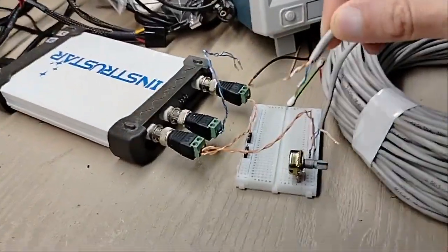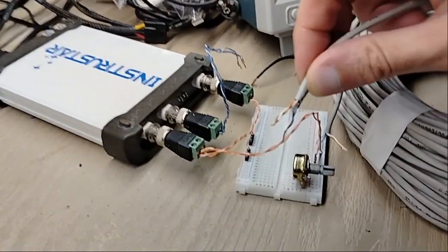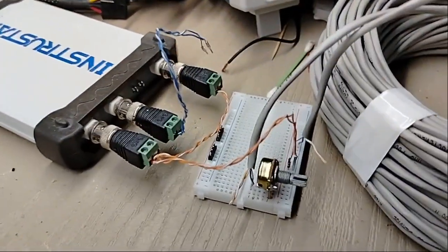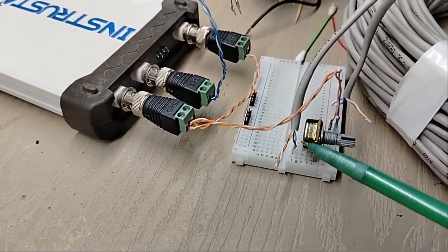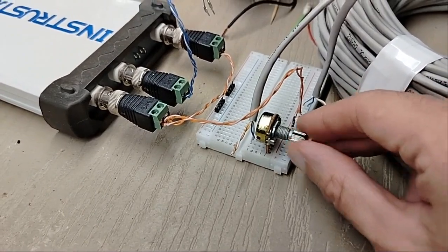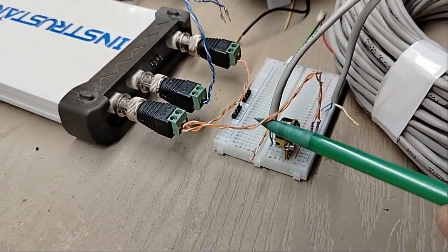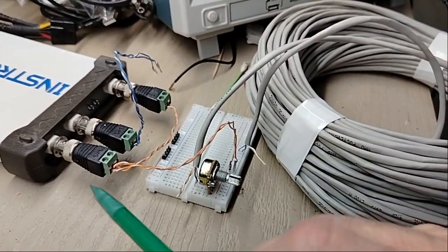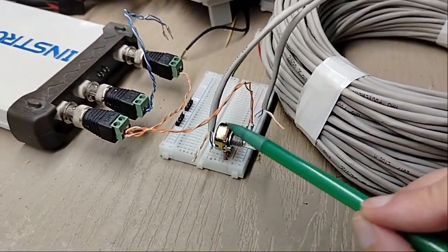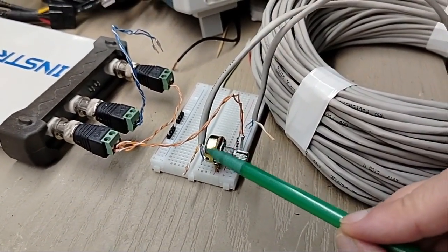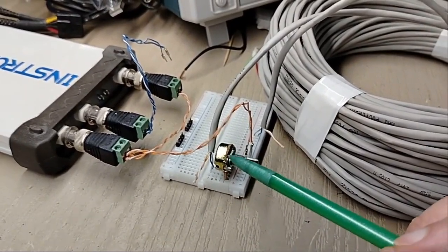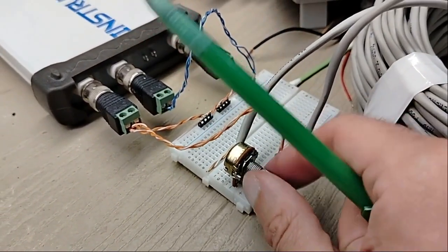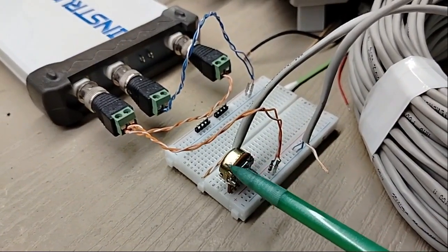It's pretty simple actually. You terminate this cable with a potentiometer, let's say this one, and by rotating this potentiometer you will reach the point at which you measure the impedance. In that case, no wave is going to be reflected back into the cable. The wave goes from the generator to the cable and is going to die in this potentiometer. So nothing is going to come back from it. Like a black hole, it is going to consume all the energy from the cable. This is a 1K potentiometer, and at this position it has the maximum value, 1K.